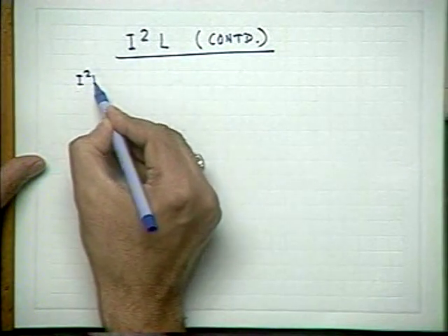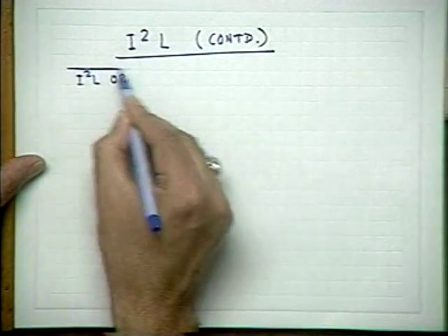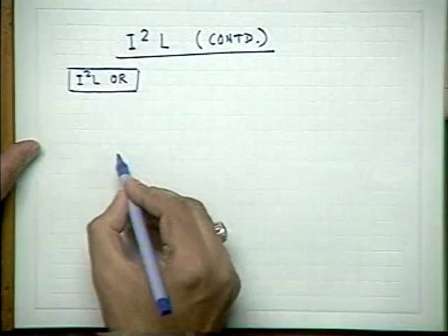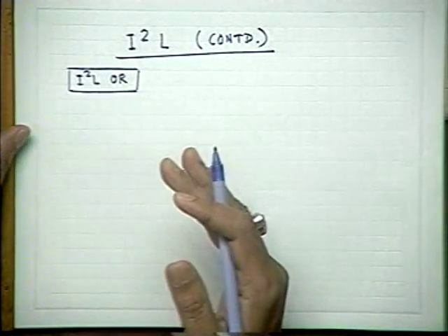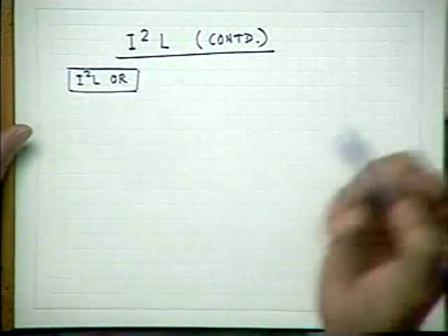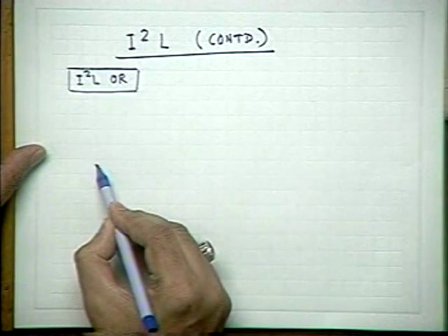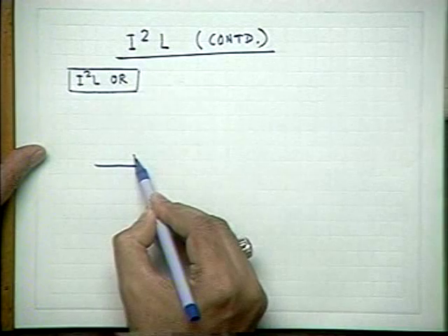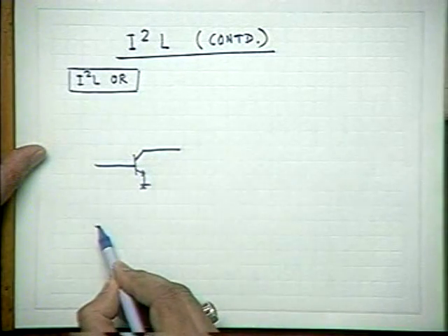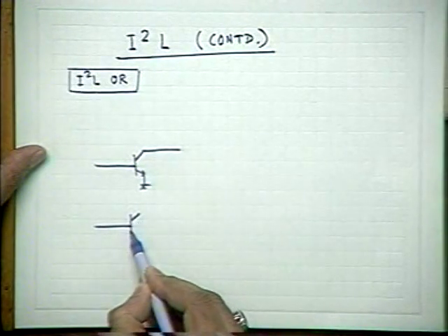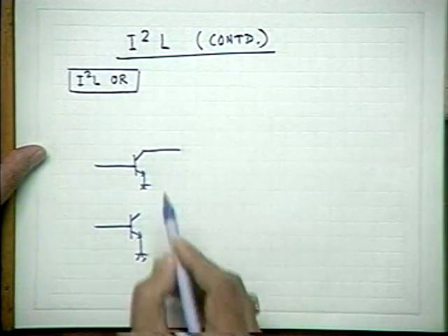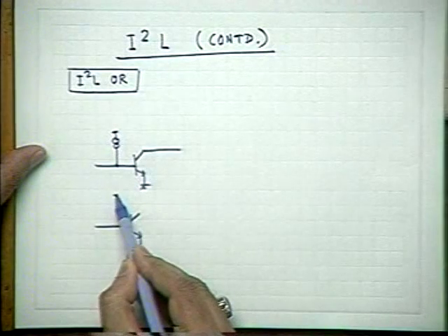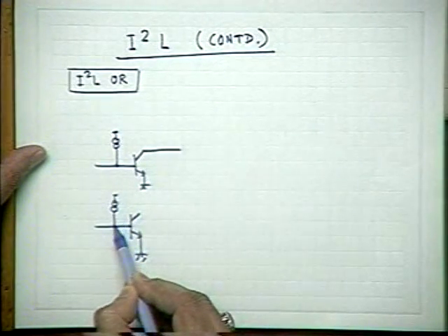I was quickly discussing all the basic gates. In this case, OR means you can conceive it as NOR and invert, or otherwise. Let us discuss that. If I forget to draw these current sources everywhere, please do it yourself.